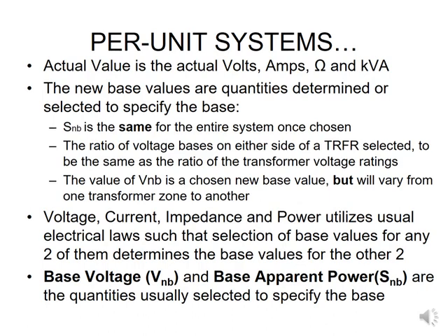They also give you the impedance of the transformer. If it was a generator, you would have the same, and if it was a line, you would have the same. In your line, you would be given your impedance in ohms, and then you can convert that because you should know what the voltage of that line is going to be.